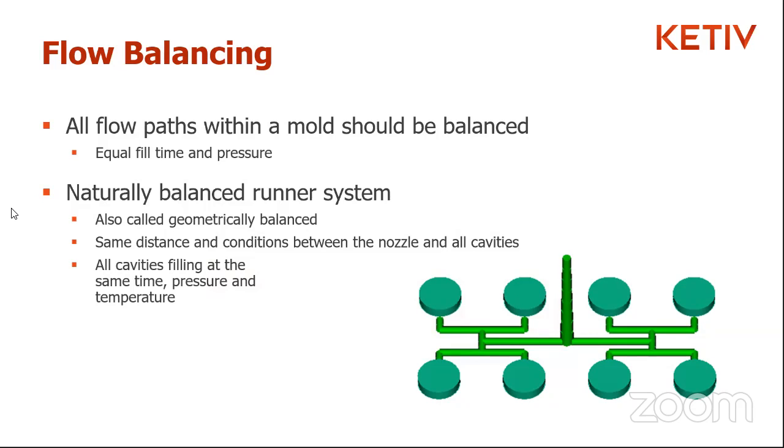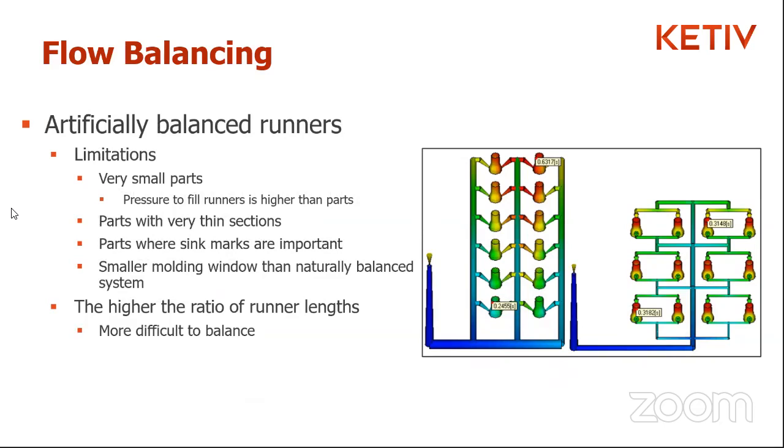Now this is a big one, where you want all of these molds to be filling at the same time, and that is the principle of flow balancing or runner balancing. Now this can lead to a whole bunch of different issues by itself, a whole bunch of different complexities. As you can see on this particular image on the left, you can quite clearly tell that the ones closer to the top of the picture definitely take a lot longer to fill than the ones at the bottom of the picture on the left.